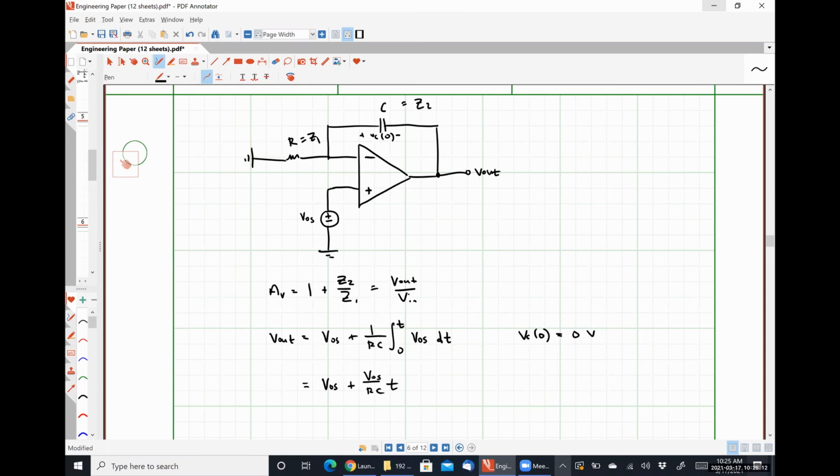Pardon? Overload the capacitor eventually? I mean, there's a restriction on the amount of voltage that could appear at the output, right? Due to the saturation distortion conditions. So as long as your capacitor was rated properly, that would never happen. But you're getting close to it, right?